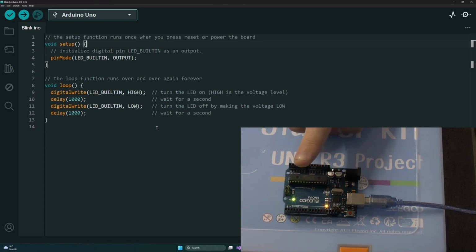I mean, for the LED, it doesn't make really sense, but if you would use the pin that's associated to it, maybe you want to control a button with that. Maybe you want to add an external button to that pin, and if you're pushing it, you want to read that the button has been pushed. So, well, you can use it in multiple ways. This is why it's called general purpose IO.